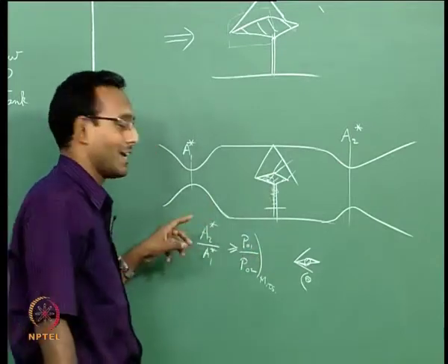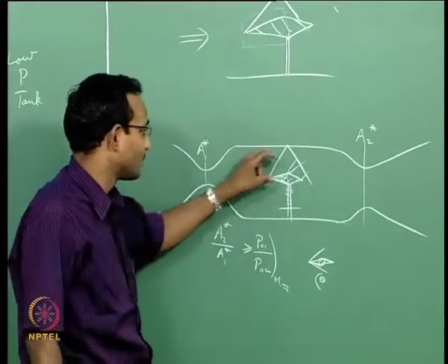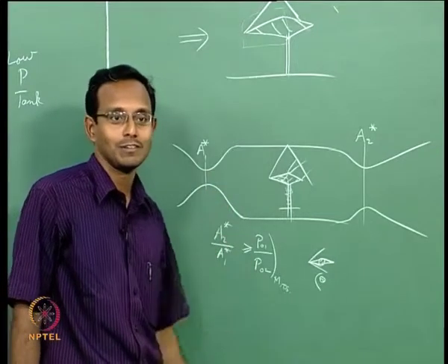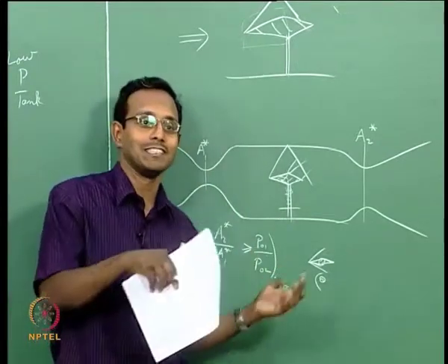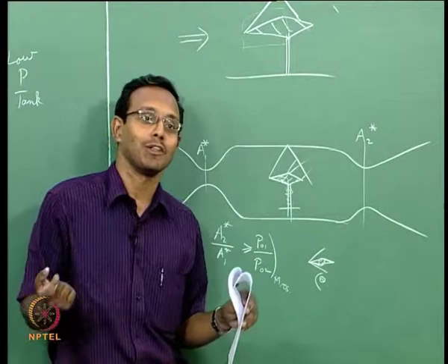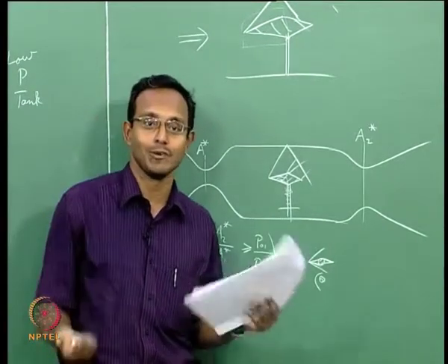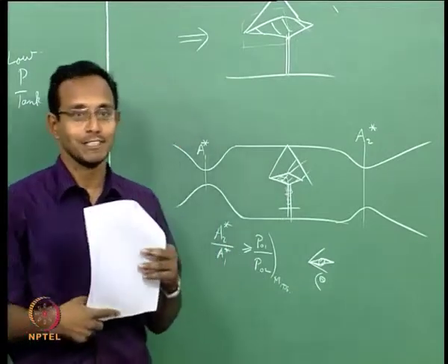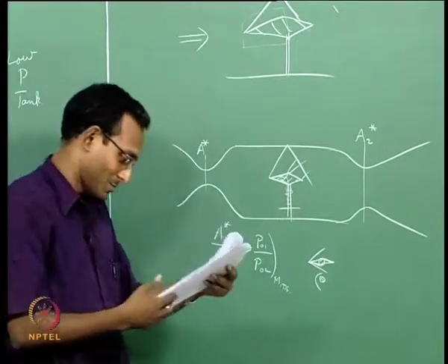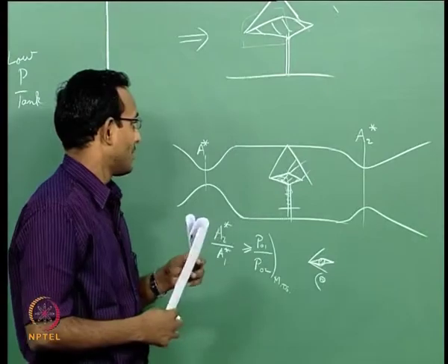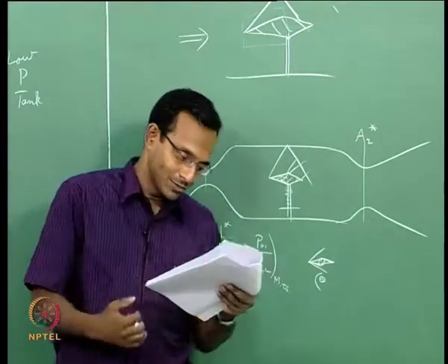Okay. So to minimize that, again I have to have small models, small holders, everything small. Of course now there will be a point where we will say structurally it is not stable if it is too small. If I have a very thin rod trying to hold a huge model, it is not going to happen. So there has to be some compromise somewhere. That's one more thing we need to think about. Now that we have done this, we can go back to transonic tunnel.